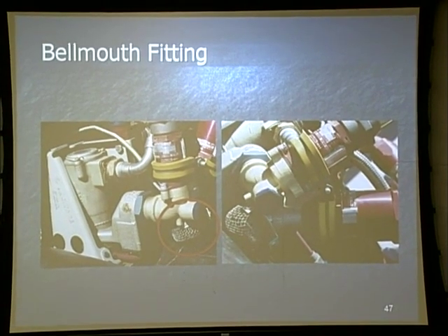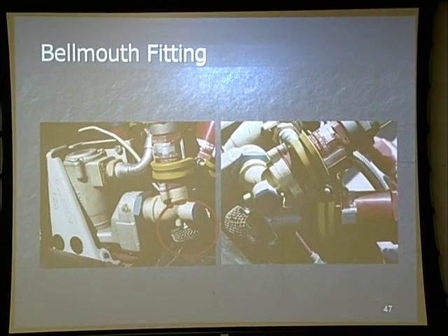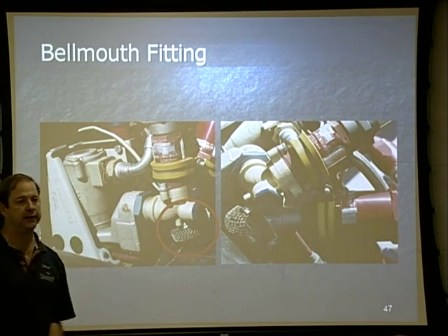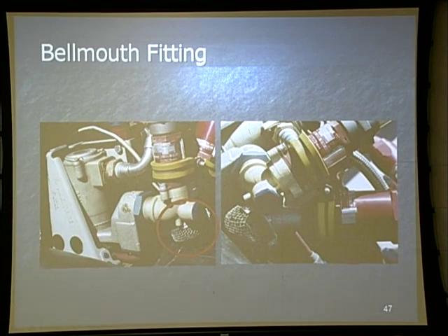How many of those do we have? Six. Should be 4. Two. One in each main tank. And they're located in the same spot on both sides. So all that is physically inside the tank. That's inside the tank, yes sir. That's inside that bladder to be exact. And this is your aft pump in your main tank. That's where it's close to.